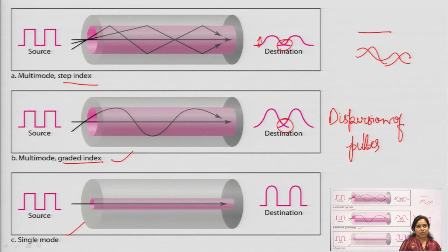Then comes the coaxial cable, where there is a single conductor of copper, which is covered with an insulator, then a braided conductor, then again an insulator, and finally a plastic covering. So, that can be used over a longer distance as compared to the twisted pair cable.